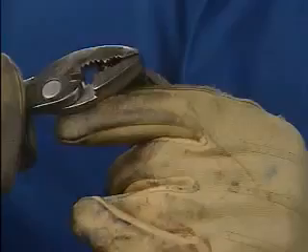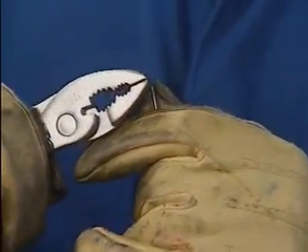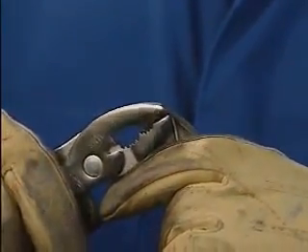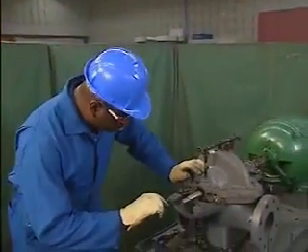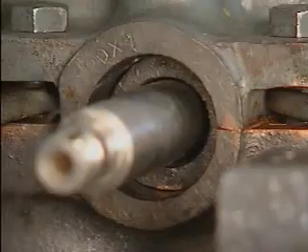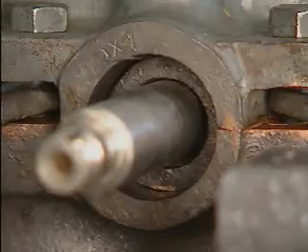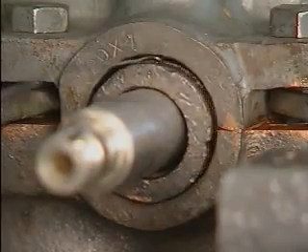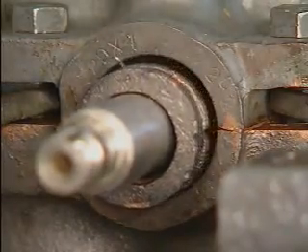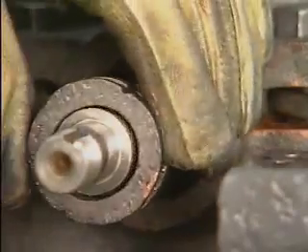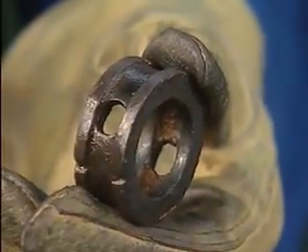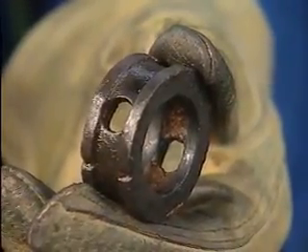To do this, the mechanic takes a short piece of stiff wire and bends one end to form a small hook. He inserts the wire into the stuffing box between the lantern ring and the wall of the stuffing box. He then hooks the wire onto the edge of the lantern ring and carefully slides it out of the stuffing box along the shaft. Many lantern rings, such as this one, are one-piece devices.